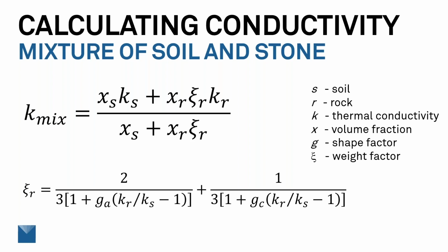that's assumed through all of this, that you would need to redo the calculation as those changes occur. So you'd need to monitor the water content if you know the dry out curve for that soil, or you would need to monitor the thermal conductivity of the soil. And then as the water content changes, you would need to redo the calculation to show the new thermal conductivity.